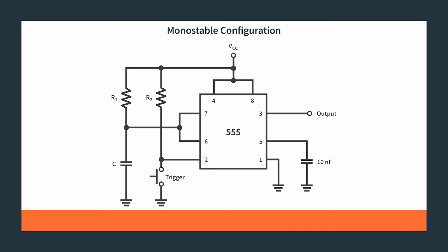And so for our practical circuit, I actually chose 100 microfarads and 10,000 ohms. So we get a time constant of around a second, 1.1, 1.2 seconds, which we will see. But it's very, very straightforward. That time constant is simply 1.1 times RC, and it's this R1 and C that actually controls that. So this is not a great way to understand what's going on, so let's switch over to the other view where we will see what happens internally.